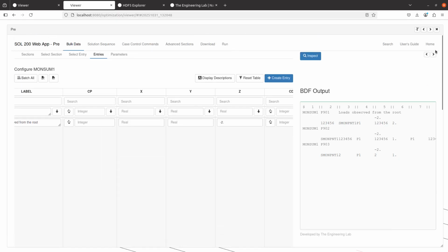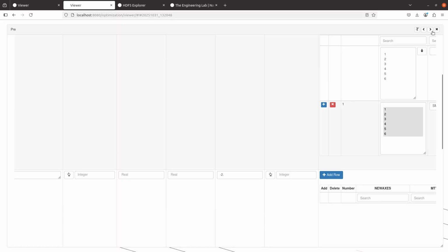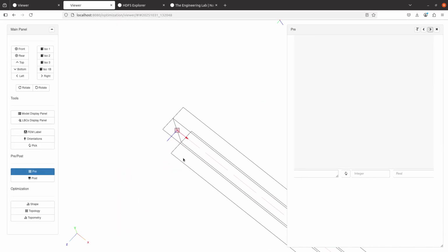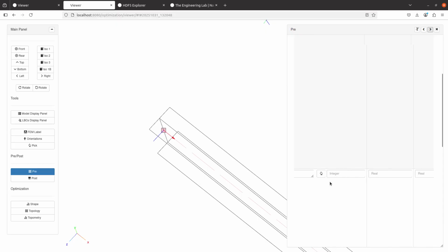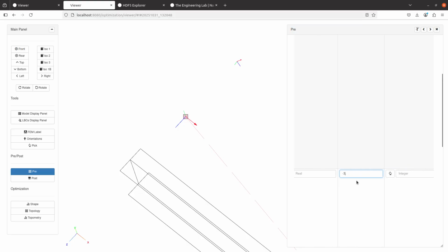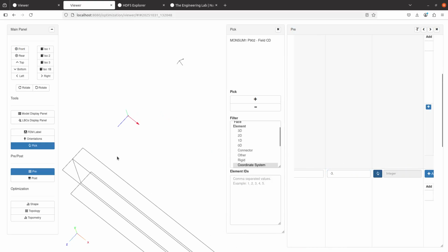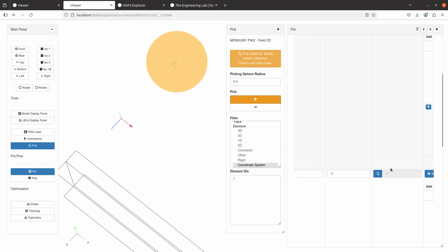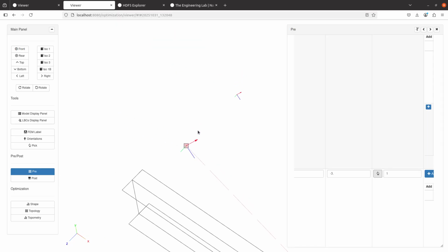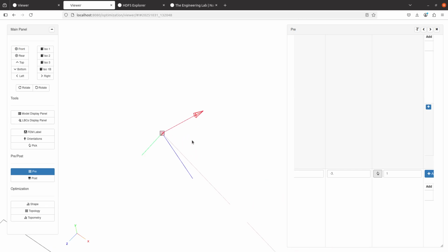Let's move it to maybe negative 3. So let's go ahead and move this to negative 3. This is the existing monitor point. Let's move it to negative 3. So now it's going to be in this region somewhere. This is our newest one. Now let's update the orientation. This is where we select a different coordinate system, and you'll see the orientation is different. You'll notice that this orientation is not parallel to the coordinate system that we used.